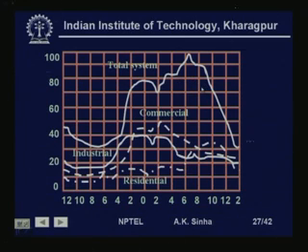Now, whenever we switch on our supply, we get the power. When we switch on, the load has increased. If we switch off, the load has decreased, and we get this power as soon as we switch on. How does this power system work? How does it provide this power immediately to us? Well, in a power system you have the turbine and the generator set. These are rotating at high speed. So, the inertia of this rotating mass stores a large amount of kinetic energy.